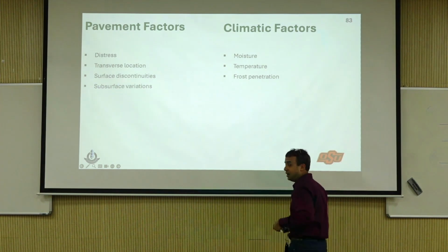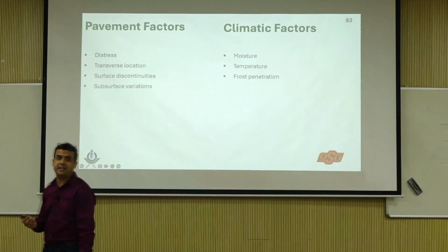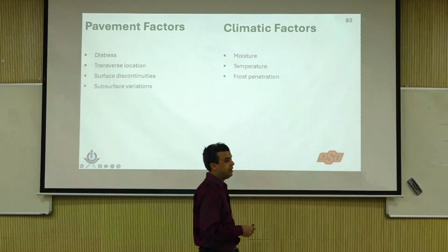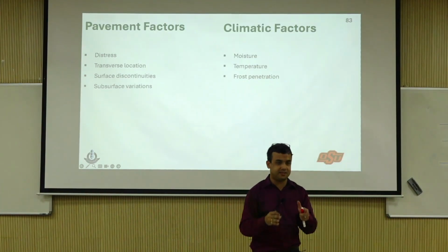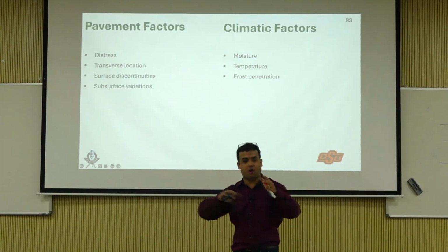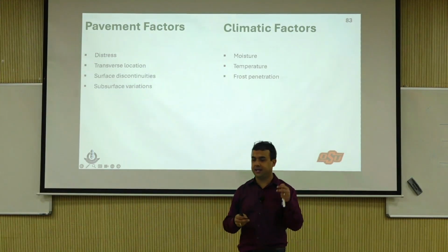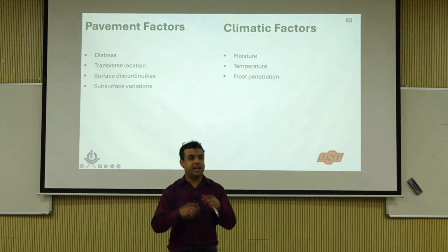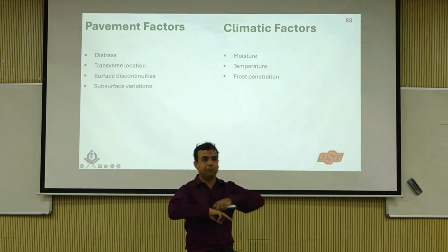Subsurface variations. I was once working for the Idaho Transportation Department, they gave me some FWD data to help them analyze for some rehabilitation planning, and we had about 20 miles worth of data. We were analyzing it and at one place the numbers were just crazy. All of a sudden deflections were almost like a step function. I said, something is going on here, go and take a look. And they went and looked. They actually saw an underground pipeline had burst over that location, and it was completely flooded.